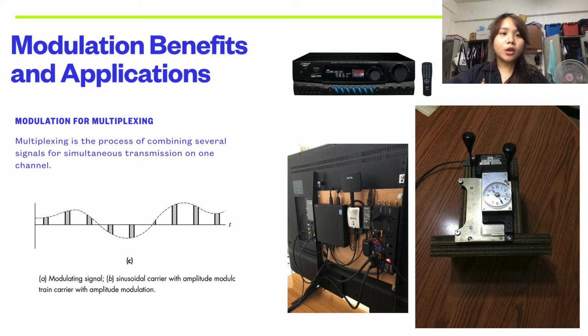For example, code division multiple access (CDMA) assigns a unique code to each digital cellular user, and the individual transmissions are separated by correlation between the codes of the desired transmitting and receiving parties. Since CDMA allows different users to share the same frequency band simultaneously, it provides another way of increasing communication efficiency.